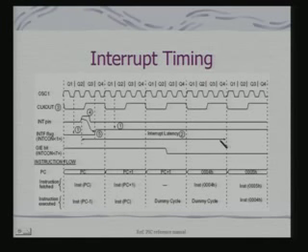Now, this interrupt latency is a very critical component, because this is a hardware latency and there would also be a software latency. These two things have to be taken into account while designing an application, because I need to satisfy interrupt constraints. What kind of constraints? Because I am making a system which is situated in the external world, and if we assume that there will be interrupts generated from an external source, I need to know the frequency with which the interrupt is expected to be generated.